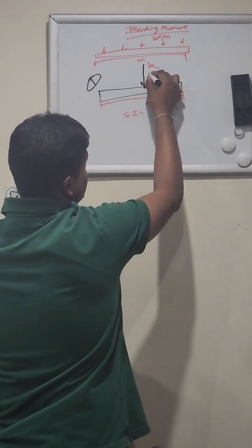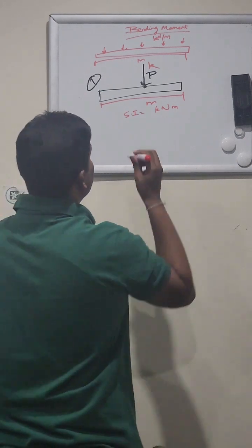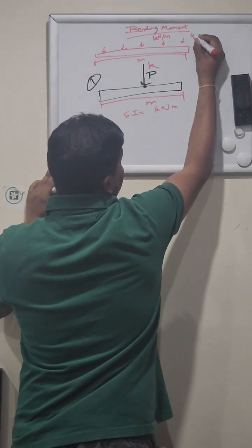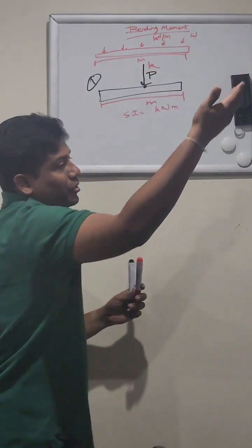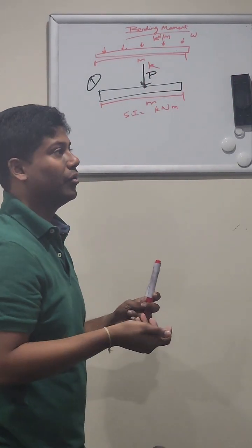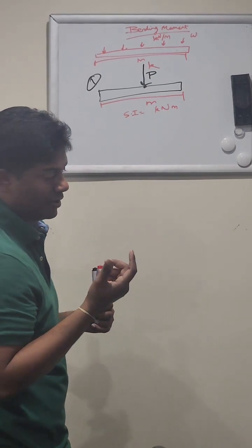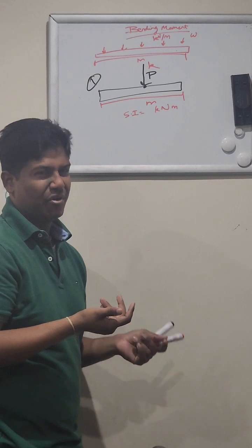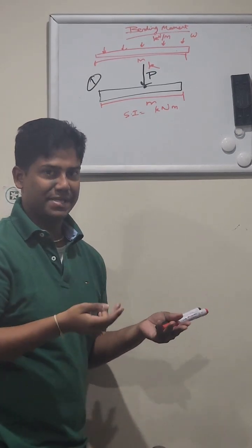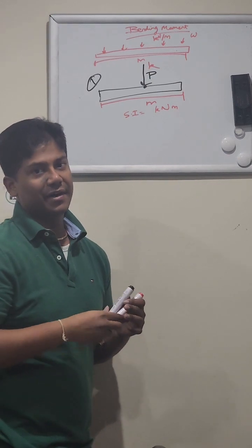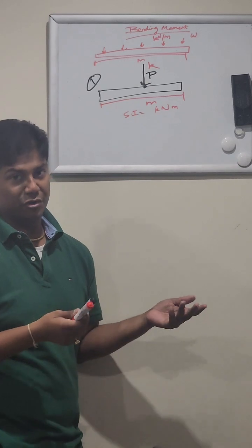Usually a point load is denoted by P, which is known as point load. UDL is denoted by W. It considers the effective load width, or I should say the tributary area, the right terminology. Both terminologies are important. The load width is more of a basic understanding. The more advanced concept is called the tributary area.